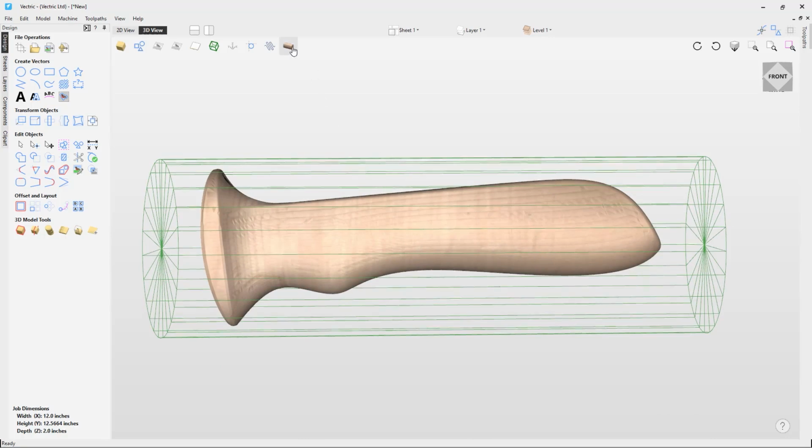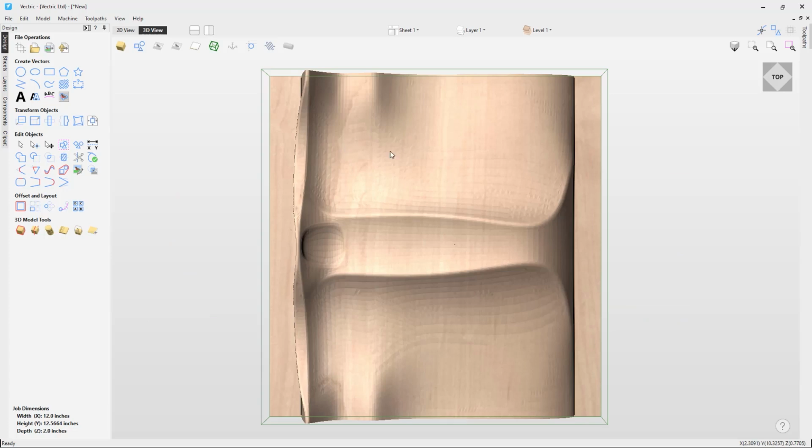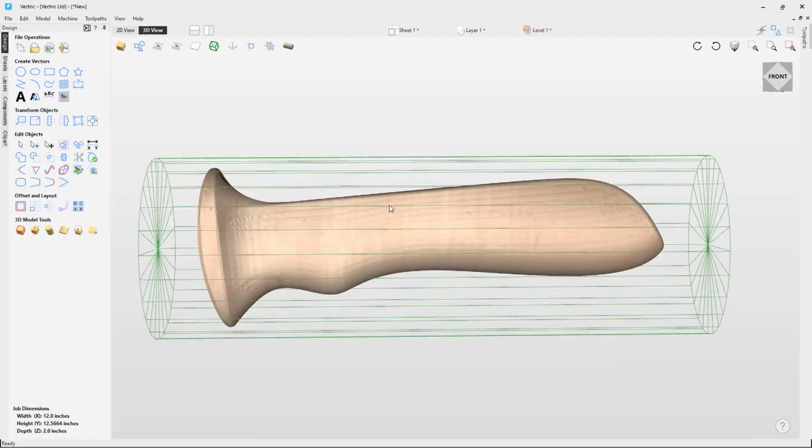One thing to point out though is if we go up to the top here in 3D view and we click on this icon here to show you the flat view, this is actually how the software interprets this job. What the software is doing is creating a 3-axis flat job, and it will wrap it around the y-axis. So currently, because I'm machining along the x-axis and my rotary is along the x-axis, that means all the y moves will be wrapped, in this case to the A-axis. So what the software will do is actually machine all of this flat, so this is how the model will be, and then the role of the post-processor is to wrap the y-axis moves into A-axis moves, which will give this result when you come to actually machine it on the CNC machine itself.